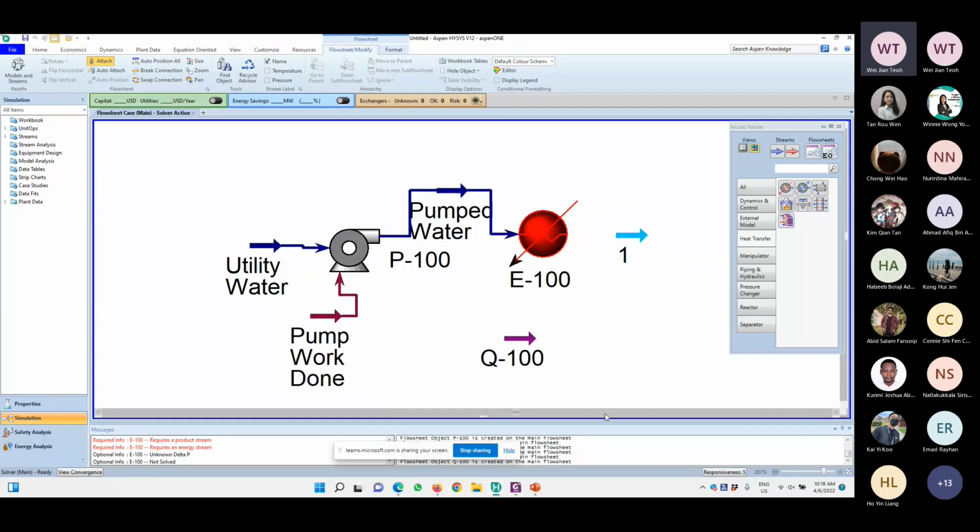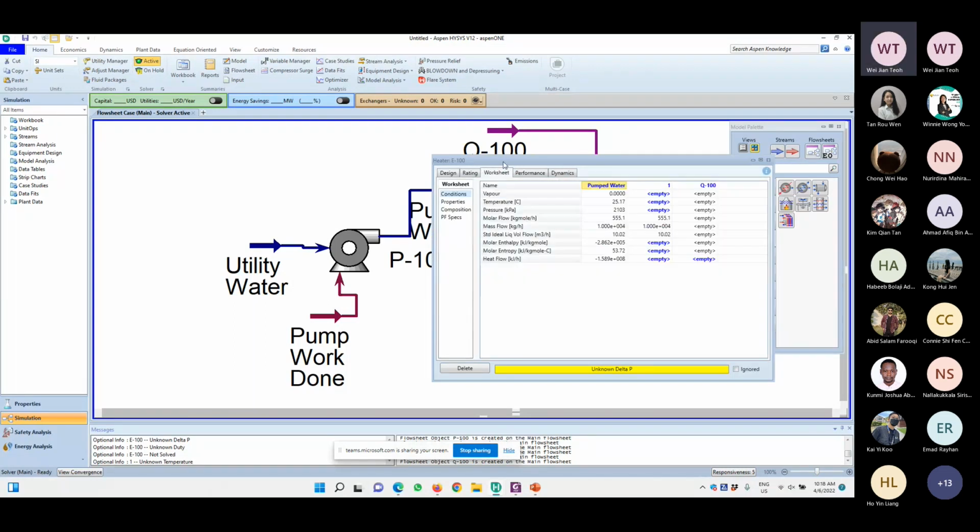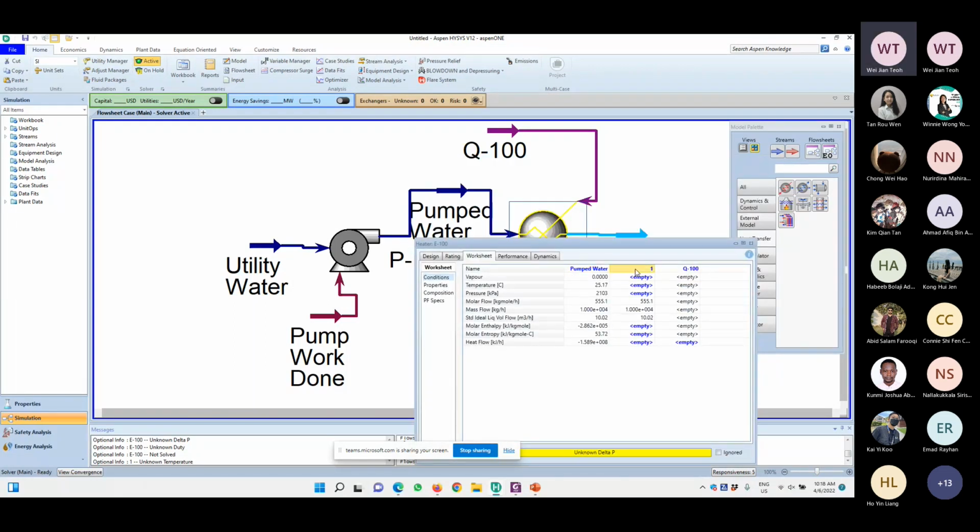So let me just look at attachments. I'll just drag here. So the inlet is on the top for a heater. And I just drag here. So this heater has all the required connections. Now I'll just specify it. Double click, Worksheet. I'll change this name to heated water to boiler. Then this will be a water heater, let's call it heat duty.